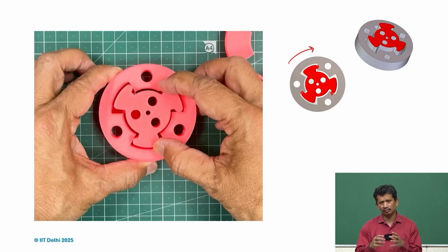So, you do not have to make conformal surfaces with very tight tolerances to bring something to the center or align the two parts. Just with this kind of constraints provided, you can relax all the requirements and still get a very good alignment, and the thing can fall in the center.